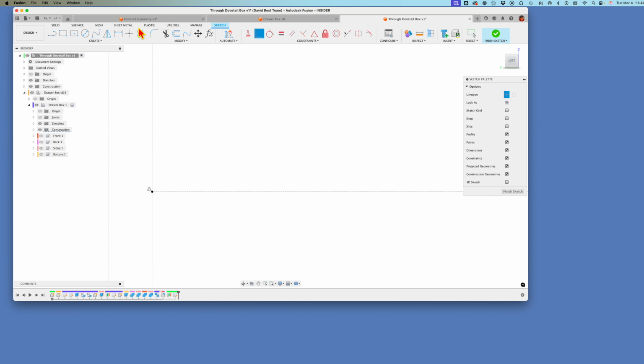All right, now let's start making a pin. Let's do half a pin. I'm going to turn off the construction line. We'll go to the line command, and let's do a line from here down to there and down to what I'll call our origin. So there's half of a pin. Let's make the front part of that coincident with the front of the drawer.